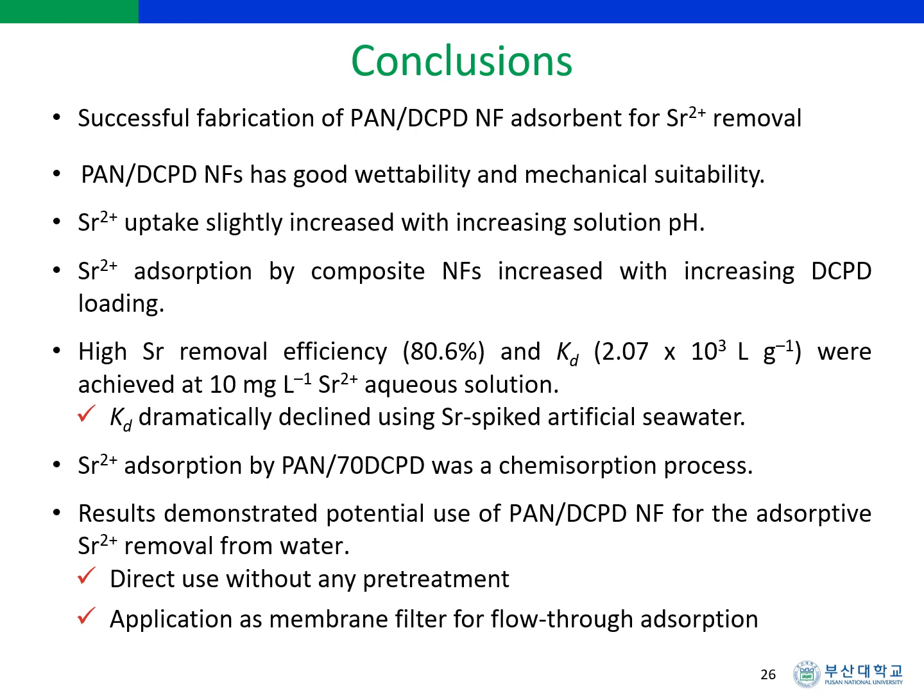PAN 70 DCPD nanofiber, as a dead-end membrane filter, exhibited superior removal efficiency over pure PAN nanofiber. However, further studies are required to verify the potential field application of PAN DCPD nanofiber as a composite membrane for the adsorptive filtration of strontium-90 in water.